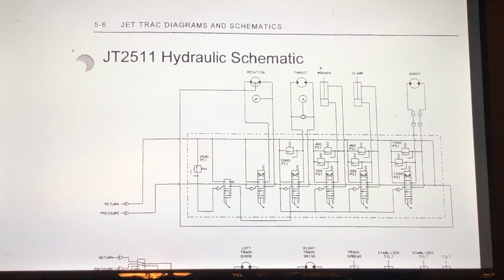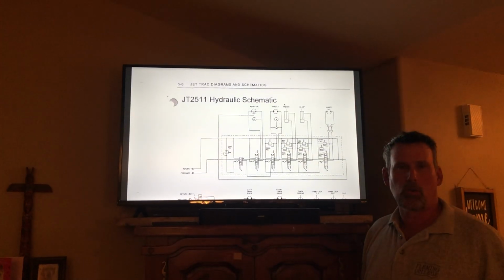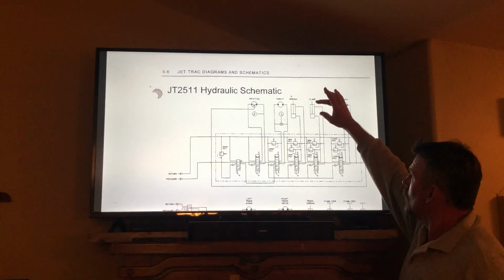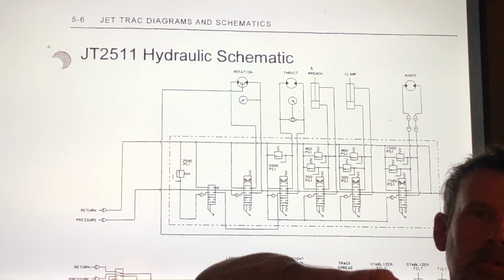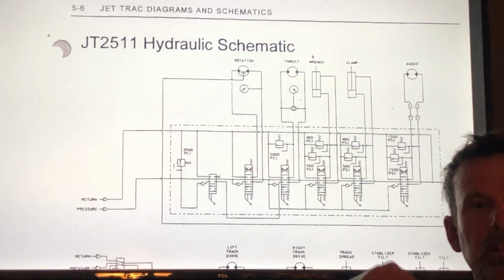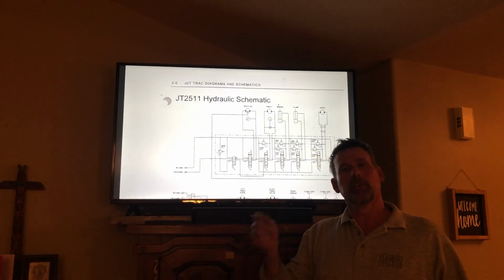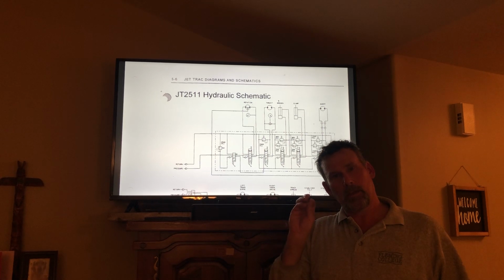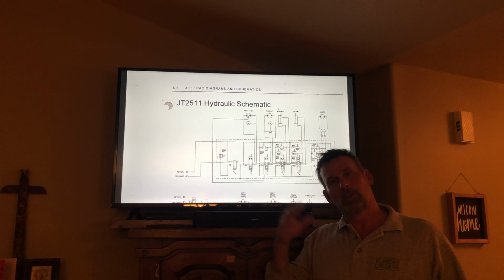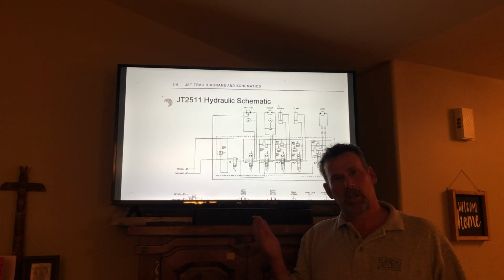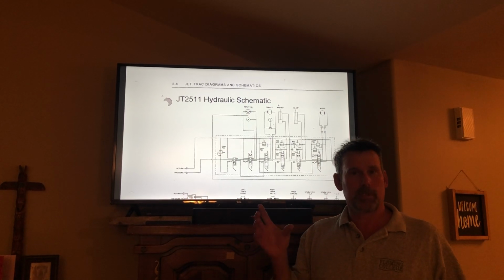And then the second part of this question, why is it different than the rod end? Okay, so we look here, you know from Hydraulics 1 that the rod end of the cylinder has less surface area than the base end. If you have the same amount of pressure going into that cylinder, you're going to have different force on each side of the cylinder because of the surface area.